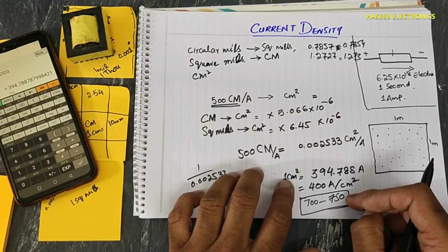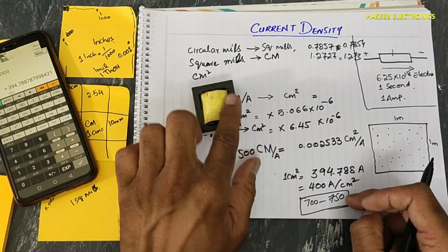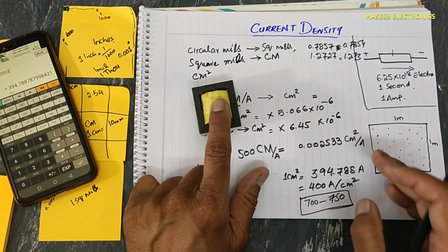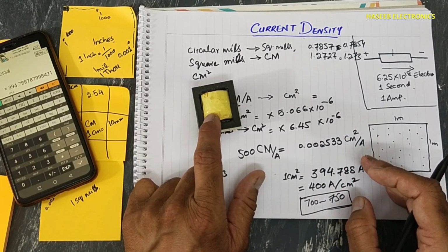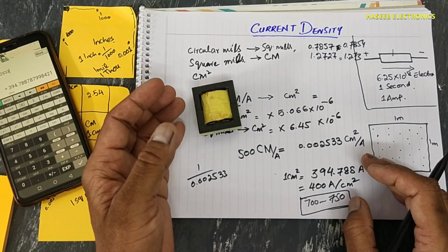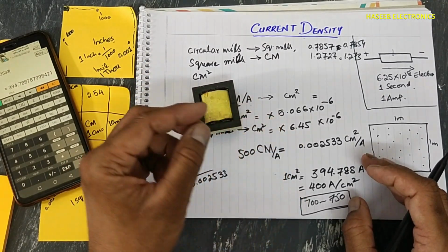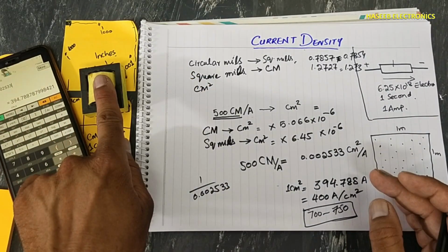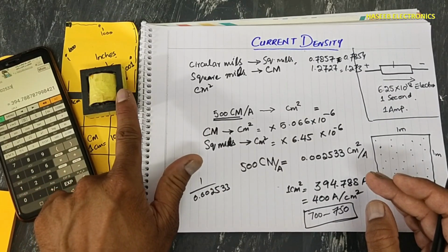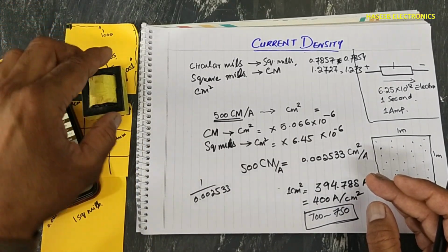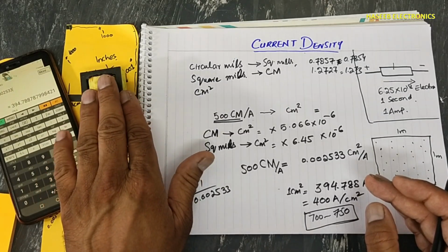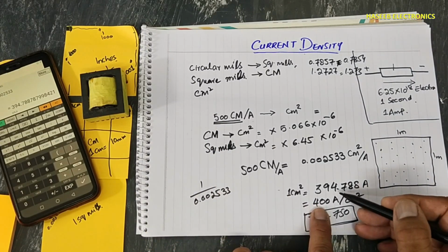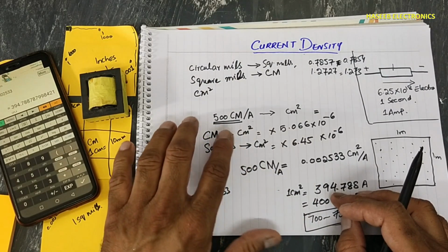So when we are calculating, using the proper area product, which type of topology we are using, what is the frequency, what is Bmax, whether we are using Tesla or gauss. If we change to gauss, then we need to change the formula for gauss. When we select proper frequency, proper Bmax and proper area product, we are selecting the proper switching topology. At that time, if the current value in calculation becomes this one, the transformer will work normally.